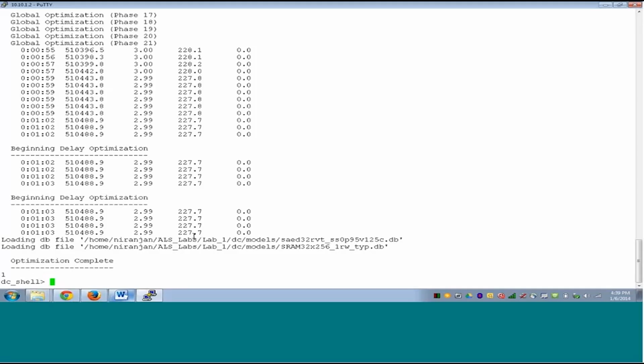So I usually try and make sure that my constraints are all right and try to decrease the runtime, because we do not want big runtimes for blocks. Each error, and then each resolution of an error, will mean that much time added to the block. So it's difficult to get that block out in time for the backend. It's very good practice to review this compile log to see how much time it is taking once per block, right? When you start synthesizing a block.